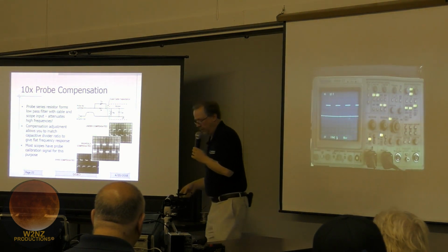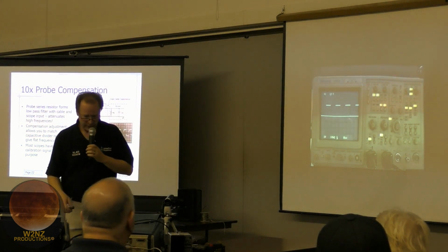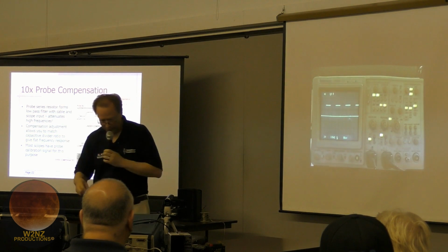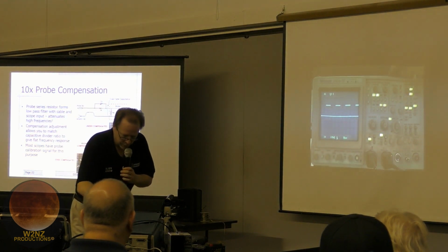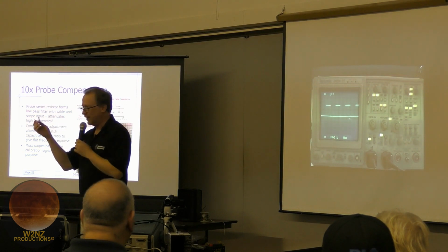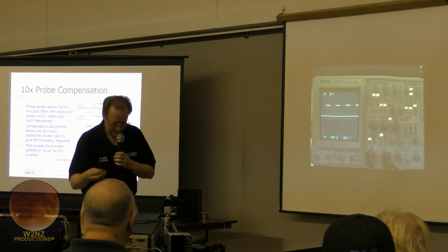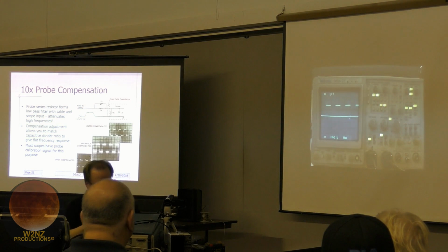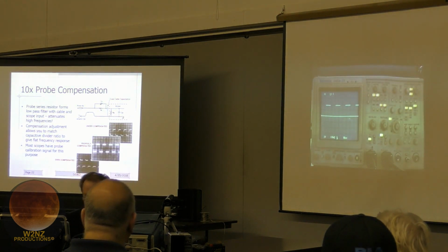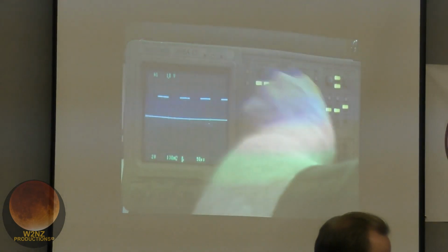Okay. So how many of you have looked at your probes and you've seen the little hole that says compensation and said, what's that for? Or you get the probe and the probe came with this little screwdriver, like, what do I use that for? Okay, that's to adjust the compensation of the probe. Let's actually go take a look at that. All right, let's put this down for a second. Reconfigure my probes here.